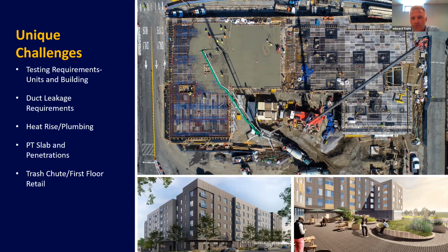PT slab penetrations were a big deal for us here. The entire building is PT slab. Spent a lot of time focusing on that, how to do it right. Not only from a structural perspective, having to do penetrations after the fact is a big no-no on a PT slab, but also thinking with the commercial space below, making sure that the barrier from the residential piece to the commercial piece was super critical for us, learning those details, locations.